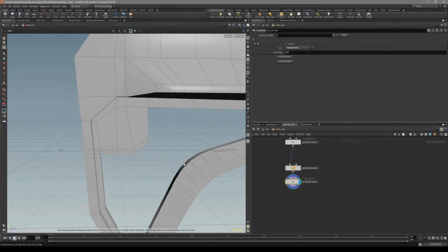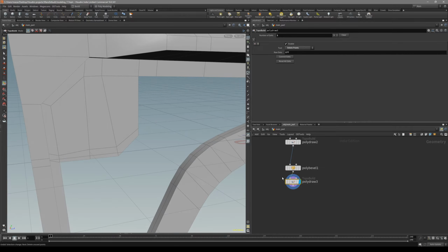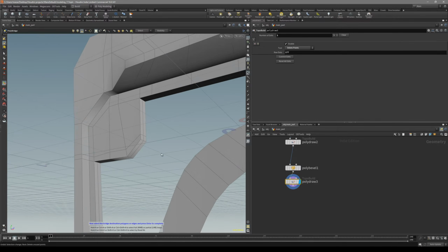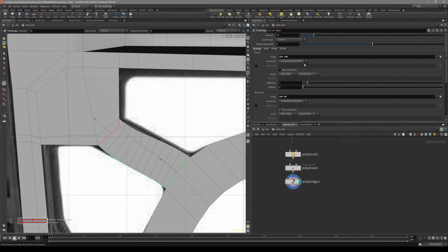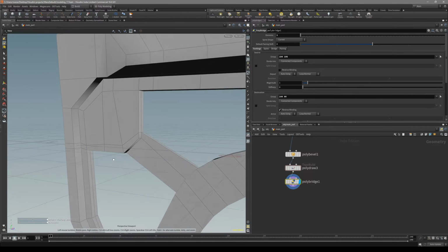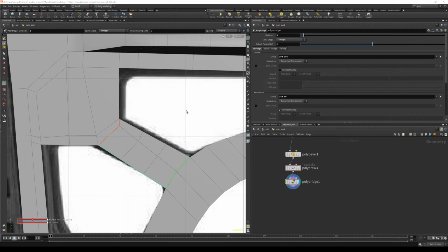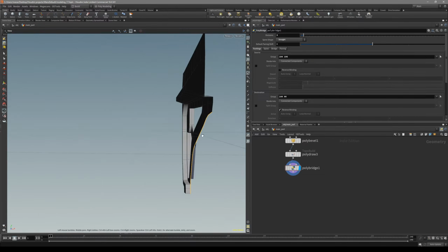So what we can do is use the stop node for the bridge. So just select these two. In the poly modeling, there's a bridge, and then it asks which polygons to select it to. Then you select these. And so in division, let's just put it to 1, and that's it. I think so. If you want more resolution, let's say 2, so it's concave, so you can put it to straight.